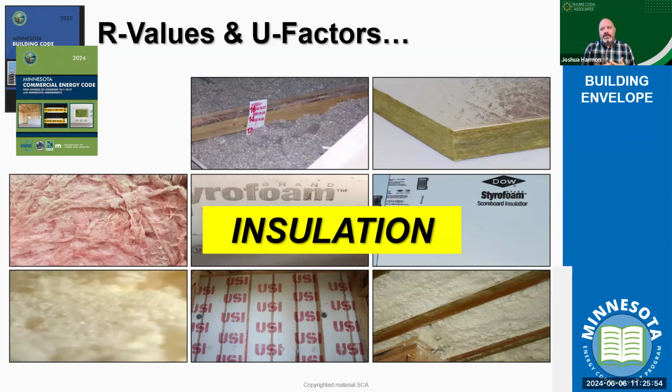Knowing how these systems are being utilized gives us the ability to say, no, this is also the air barrier. So if we're going to modify and go to an R20 batt, then we need to also identify what's the replacement for the air barrier, and vice versa. So again, how can we make sure that these systems all operate well?